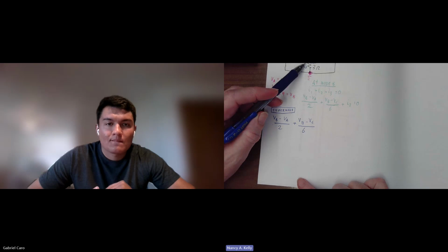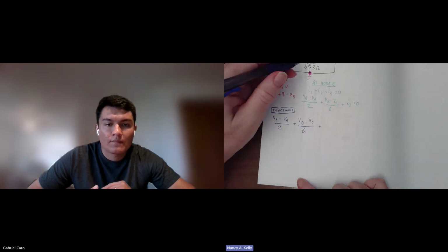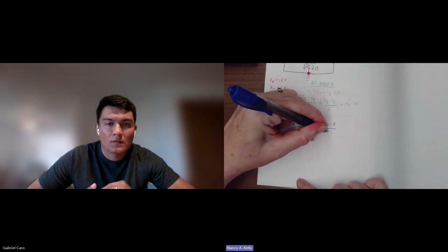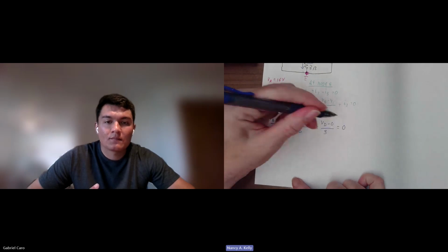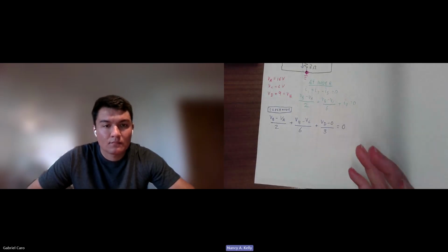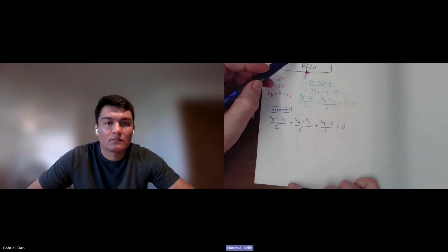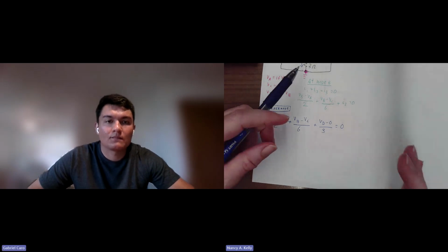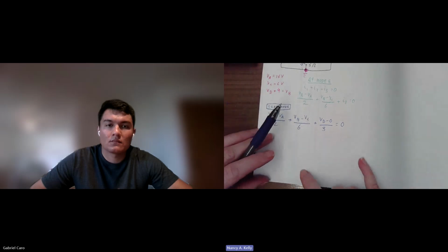And then now I'm going to talk about the current flowing out down here, okay? That current is VD minus 0 divided by 3, because that is a resistor, okay? And that has to equal 0. The sum of the currents entering or leaving a node, as I define a node, has to be 0. So Kirchhoff's current law still holds. It's just that now I've enclosed a bigger thing and I'm calling that a node. And I only do this when I have to. And it's only in these cases where I have a voltage source that I can't describe in another way, okay?